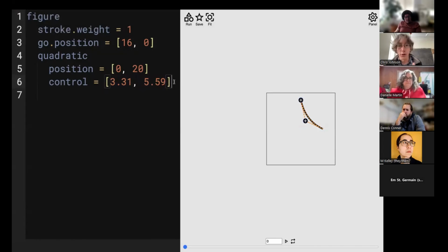So that's one quadrant. I want a full diamond pattern, so I want the next quadrant, and I want the other two quadrants. It'd be nice if I didn't have four separate quadrants to fiddle with. I want symmetry, and so there's a mirror command. Add in a mirror,